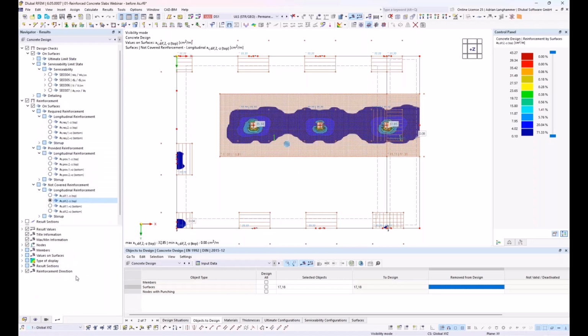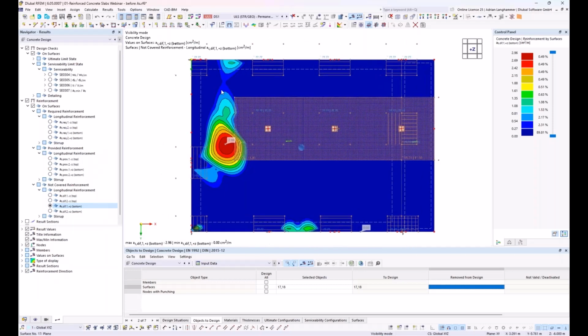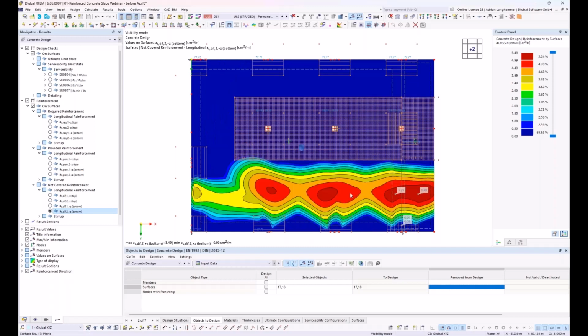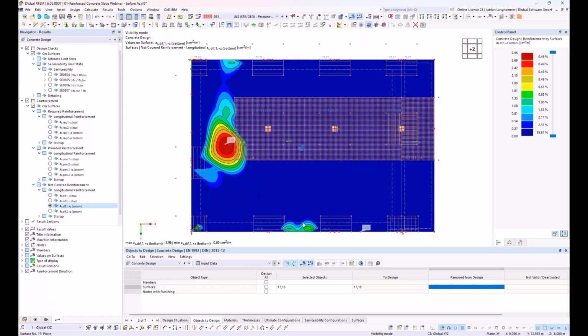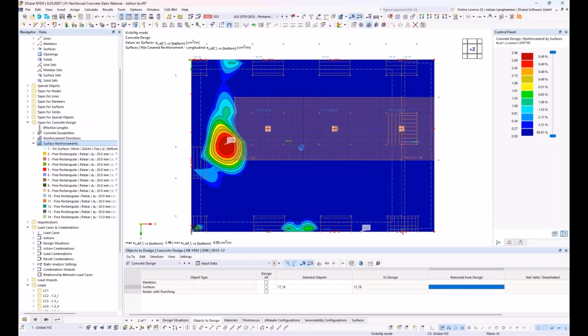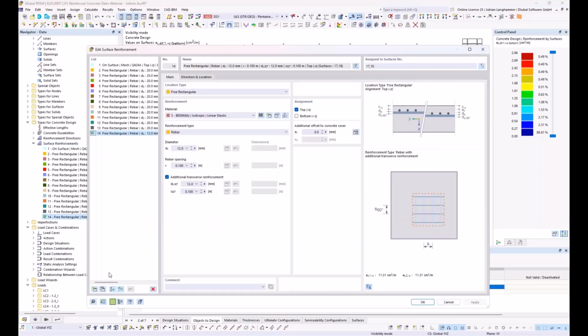And then I have to define also two reinforcement areas for the bottom side. There's an area here where a not covered reinforcement occurs, and then also here in this area, in direction 2 mainly, also a small reinforcement in direction 1. So I define for these areas also an existing reinforcement. This time I use the copy function again and copy my last reinforcement and switch to bottom.